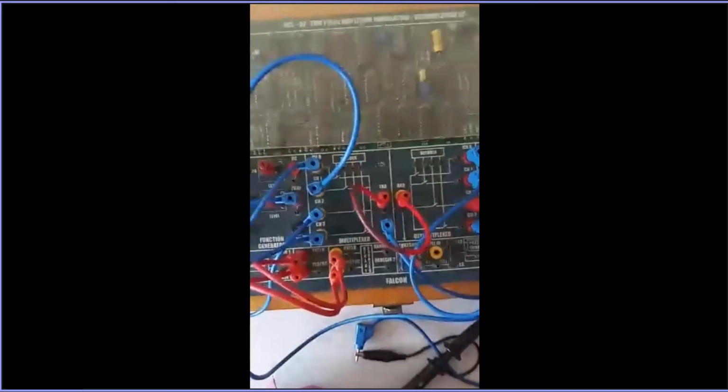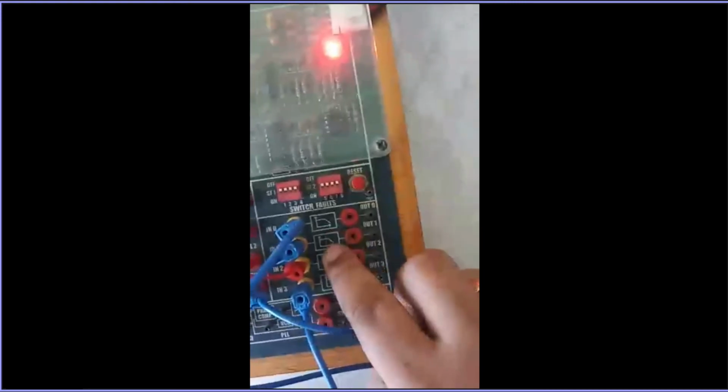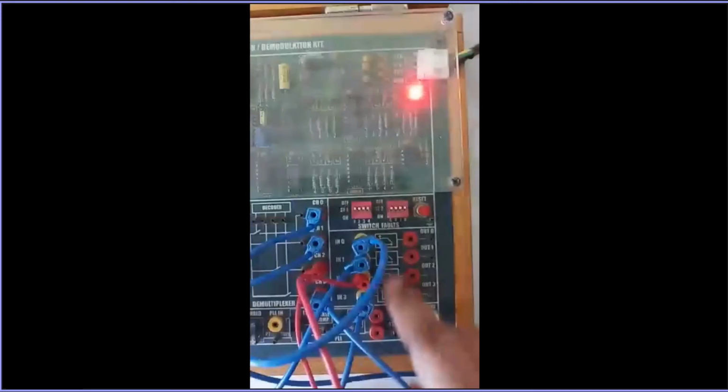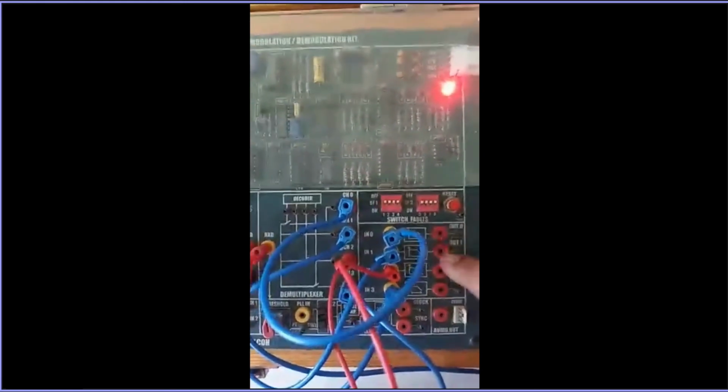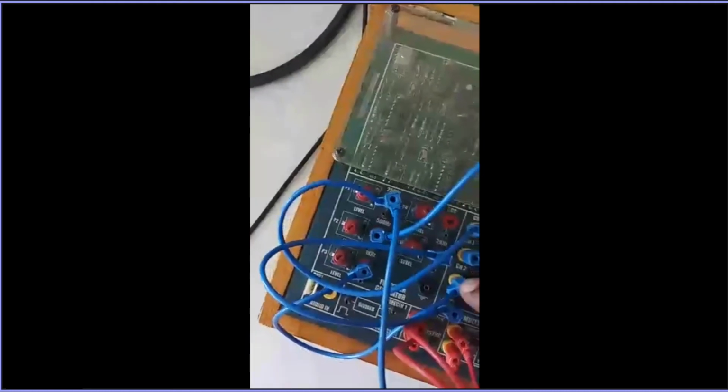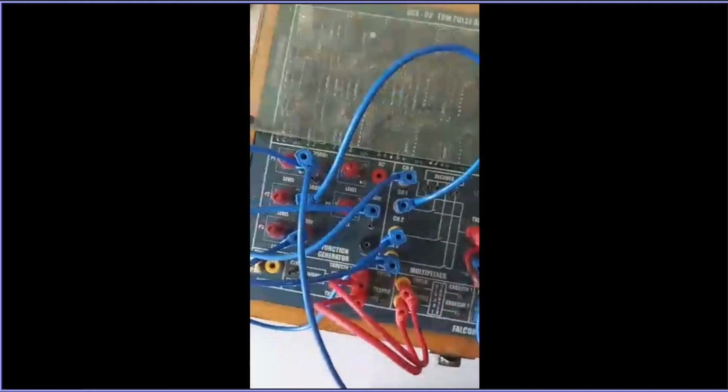And then you have the filter. You can see this is the band pass filter, 4 band pass filters. And the 4 outputs of these band pass filters will give you the 0, 1, 2, 3 channels, which are the inputs you have provided accordingly, right? So we'll see all of them.